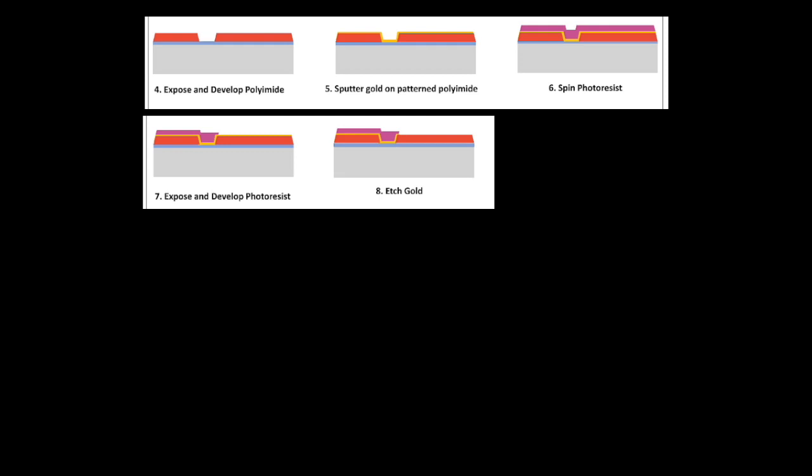This exposed gold, unprotected by photoresist, can then be etched away by a wet etching process in which chemicals wash away any portion of the gold not protected by photoresist, or by a dry etching process, which is like sputtering in reverse, where argon ions are shot at the disc to knock away the gold. So to recap what's happened here, a bunch of gold was layered down, and then a protective template was put on top of that gold so that the rest of the gold could be destroyed and removed from the disc while preserving some of the gold in a specific pattern.